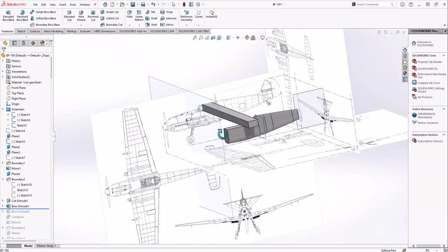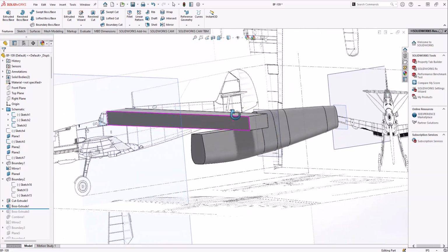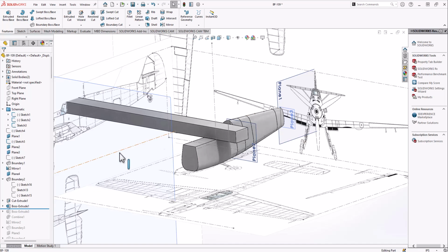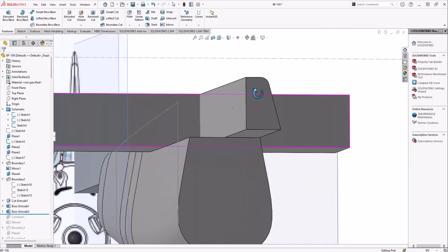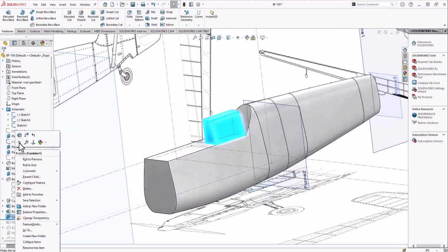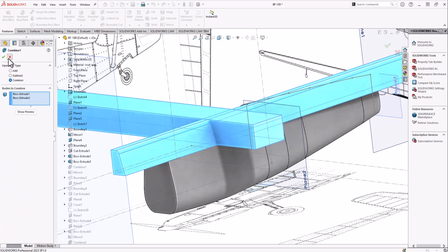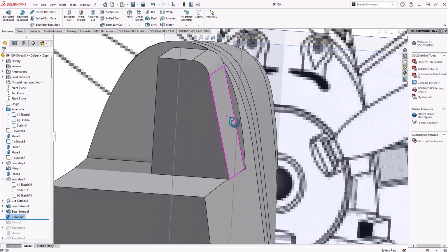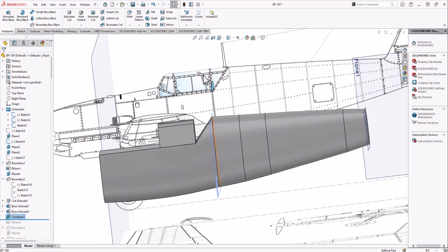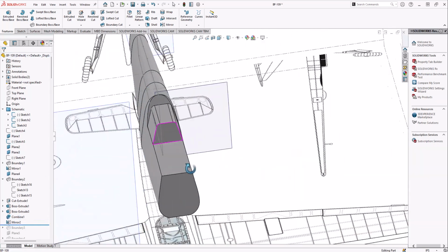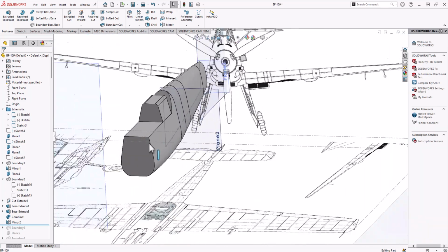So this looks kind of goofy, and what I'm doing is a common filter, like a Boolean operation, with this and the front view, in order to get the section of the cockpit that I want. So you can see I have these two intersecting, and then I'm going to use a combine feature, which in this case I'm going to take the common between the two. So it just creates this little section, which is going to be the center portion of the cockpit. And then I just mirror that like I did earlier, so it is on the other side now for symmetry.